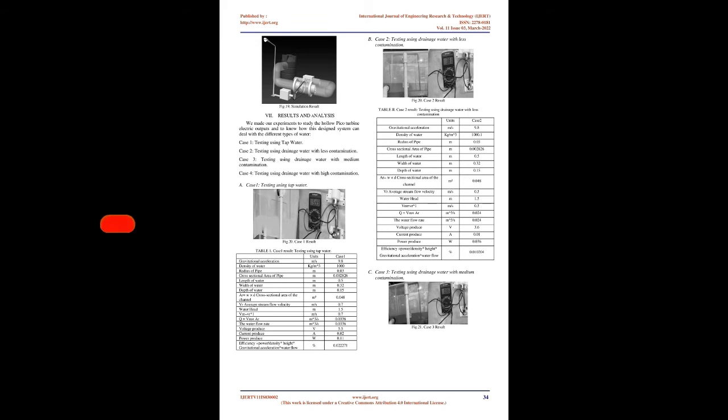Fig. 8 shown below explains the runner. It has 4 blades, and a circular hollow is provided around the rotating central axis so that foreign matter included in the water can pass through the runner. The ratio of the hollow diameter D2 to the pipe diameter D1 is defined as the hollow ratio E, which equals D2/D1 equals 0.375.